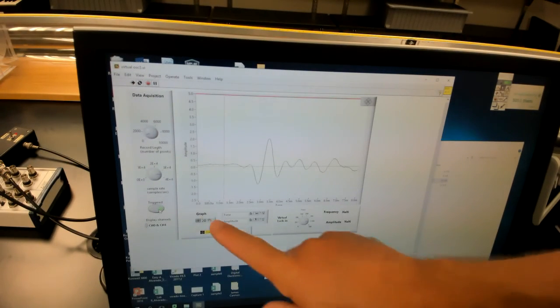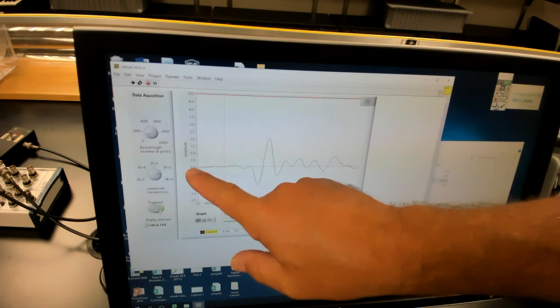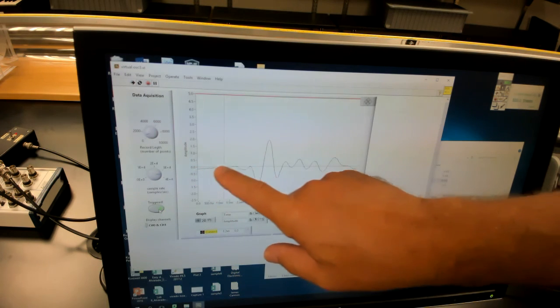What's going on is that at 0 seconds, the ADC converter receives the trigger signal from the function generator and it starts the acquisition. That's approximately also the moment when the speaker produces the pulse. If we look at the microphone signal, there's no signal for some time. There's a dead period here.